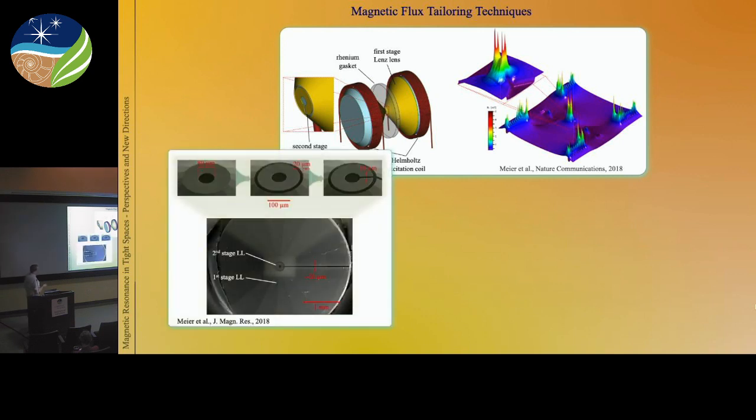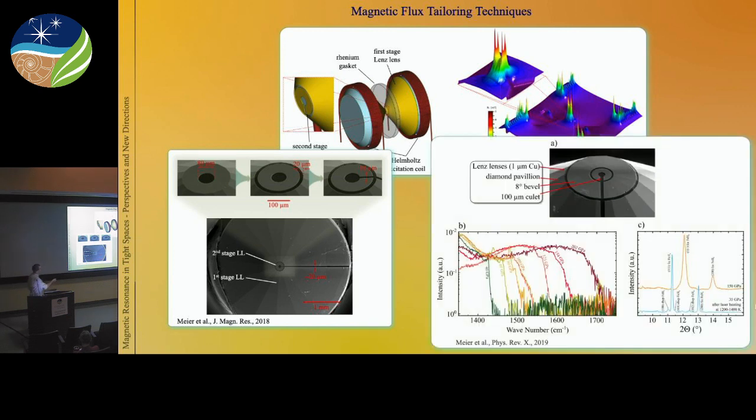And here you can see some photos of our SEM cutting and of our FIB cutting. As you can see, using a FIB, we can control the geometry of these lenses to a very satisfying degree. Of course, we can go one step further and use beveled diamonds by simply introducing a third step of induction, where we now have 3 lenses per diamond: on the pavilion, on the beveled area, as well as on the cullet here.